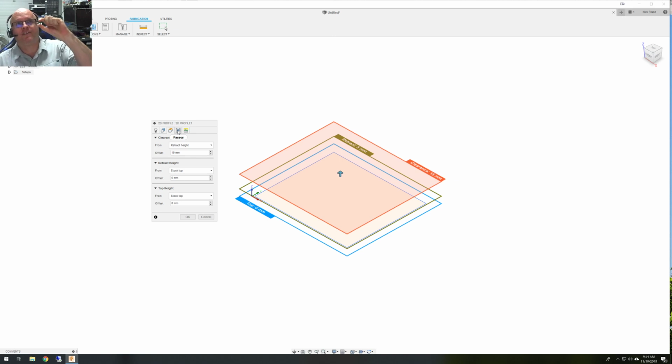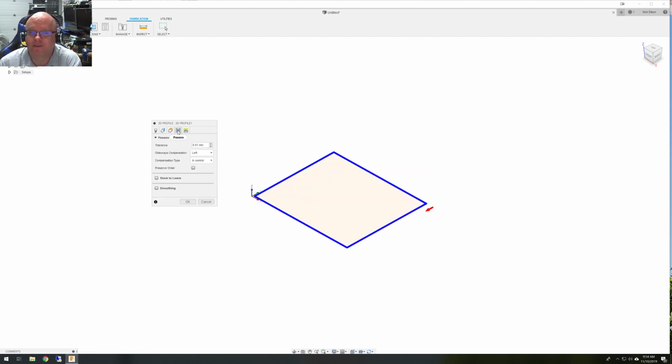My laser likes to be about 6 millimeters from the tip of the nozzle to the work surface to get the focal point in the best place. And I did a ramp test to figure that out. So I will do that myself and not worry about any of this.